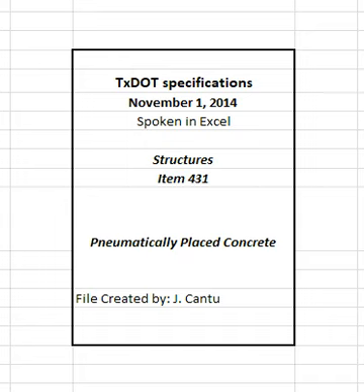3.3 Reinforcement. Place and secure reinforcement to ensure there is no displacement from impact of applying pneumatically placed concrete. Place reinforcing bars at a spacing not less than 2.5 inches.